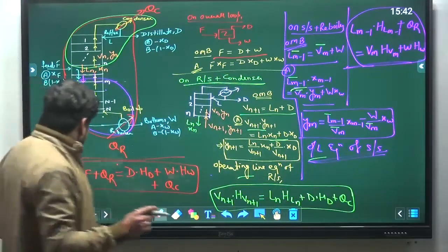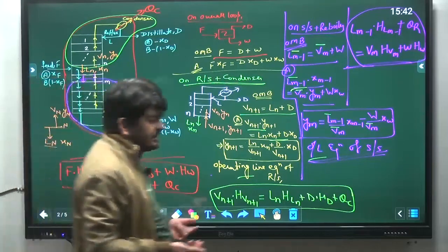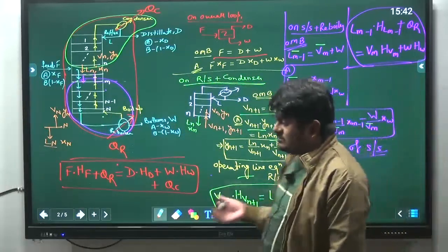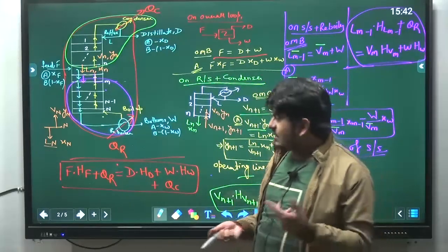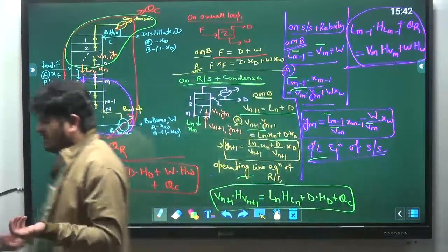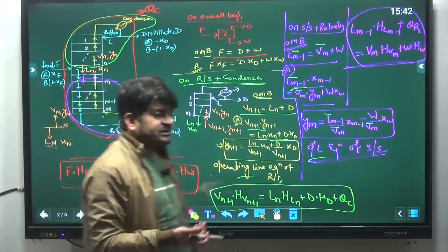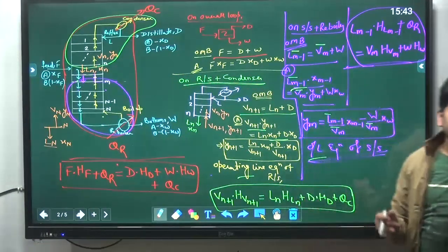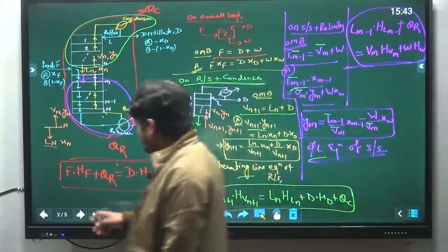Now when we talk about process designing, there are several methods to design the distillation column. In a distillation column, process designing means we want to find out the total number of ideal stages required in the column. They can use the McCabe method, Ponchon-Savarit method, distillation sequencing method, and a number of other methods. But as per the syllabus we have to deal with the McCabe method only. So we will talk about the McCabe method now.